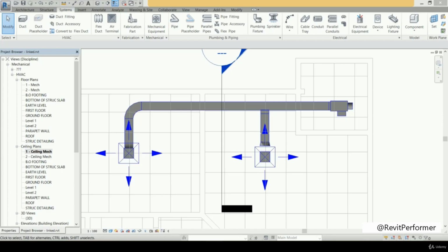But if the duct lays outside the building or at the roof of the building, the insulation thickness in that condition will be double the insulation at the inside condition or the interior ducts condition. So in that condition, it will be 50 millimeter instead of 25 millimeter. And this 50 millimeter is about 2 inches. But this is logical, to have the interior duct insulation with a lower thickness than the exterior duct insulation.